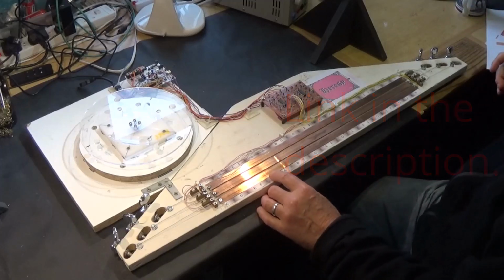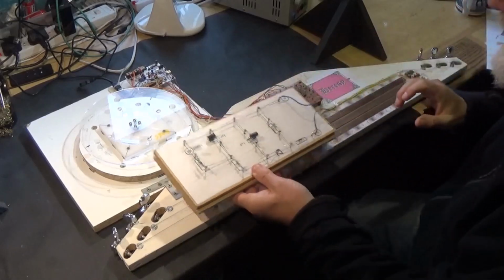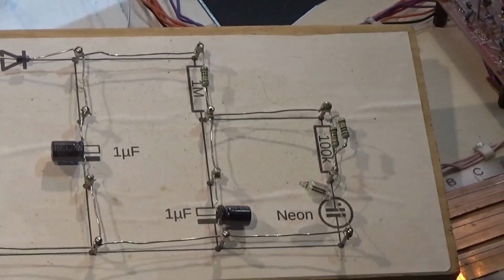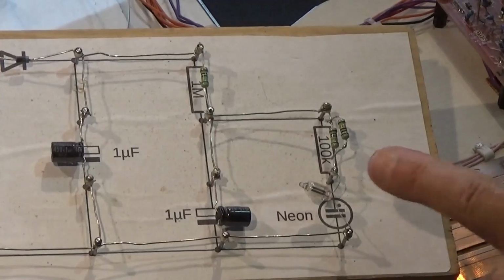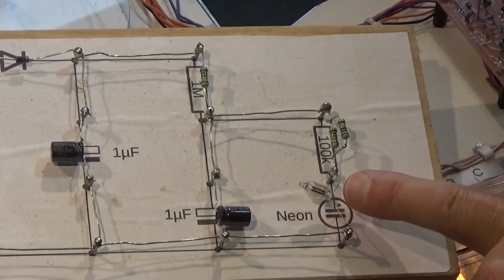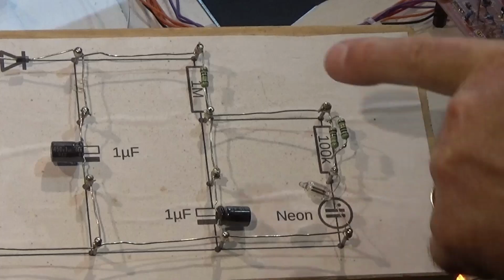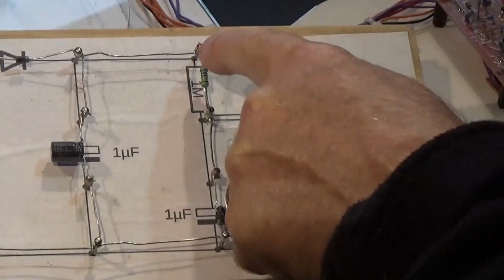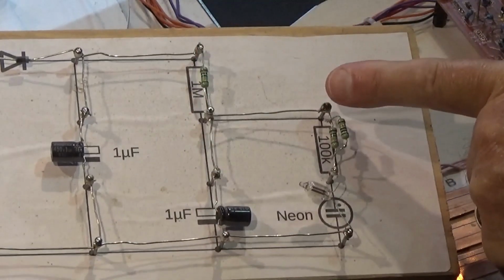So we started with, for a bit of fun, we made this little guy. Okay, so this is the business end. This is a neon. It works by sending a current through a plasma and thus emitting light. This is just a DC voltage, about 120 volts. And this resistor and this capacitor charge up until this point gets to 90 volts.